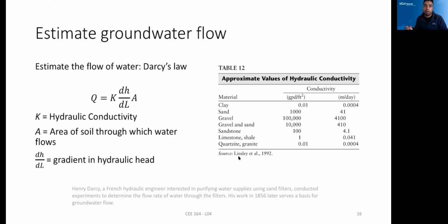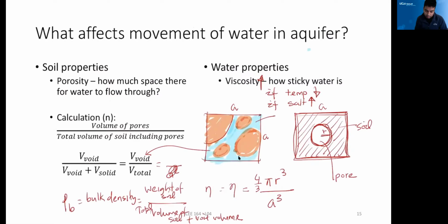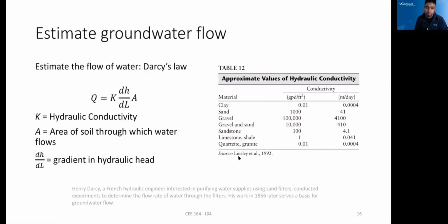Some media allow temperature to flow faster; same thing, some soils allow the water to flow faster. We know the reasons, porosity and all those factors, but as a whole we call it hydraulic conductivity. Hydraulic conductivity is a function of both soil properties and water properties that we learned just a few minutes ago, so we'll connect that. But just know that if you want to calculate how much flow goes through your system or locations, you will use these equations. So Q is the flow rate.